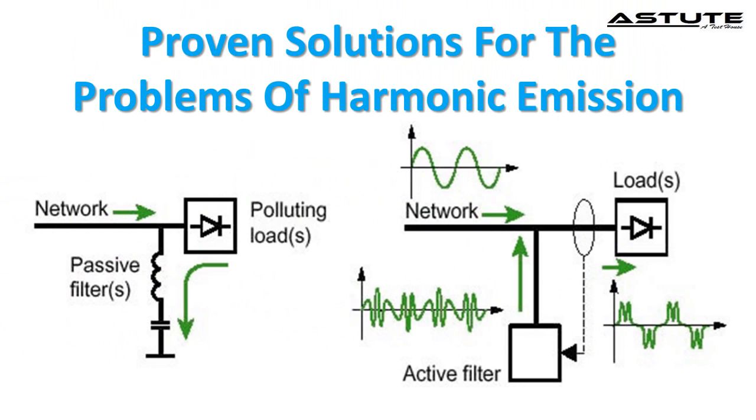There are different solutions available to remove or minimize the harmonic emission noise from the device, given below. Use harmonic filters. Use isolation transformers. Line reactors. By adding a line reactor or an isolation transformer, we can attenuate harmonic noise. Isolation feeding sensitive loads and harmonic loads from separate sources provides greater system impedance between loads.